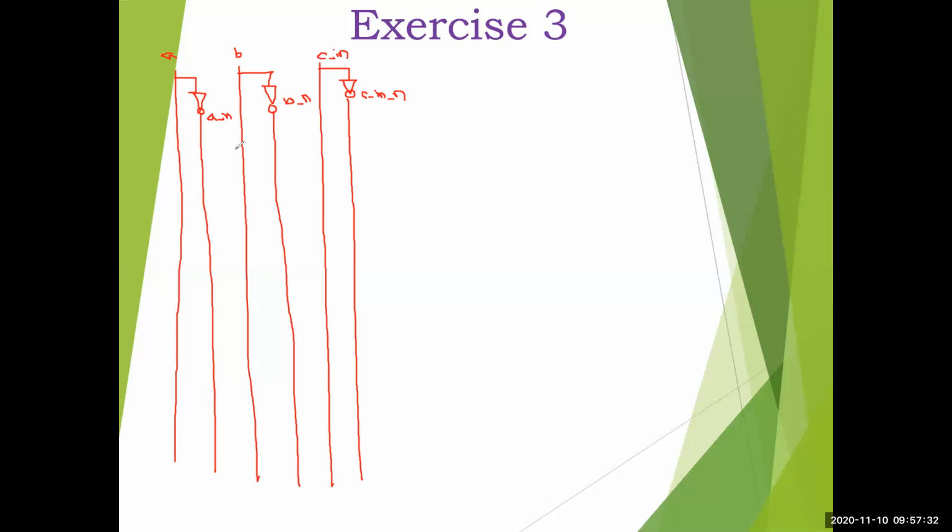First we'll do the sum part, where you have to do ABC. A, then B, and then C, all no complement, so all 3. You connect the AND gate, and this is the first output. I call it S1. It is A B C in.